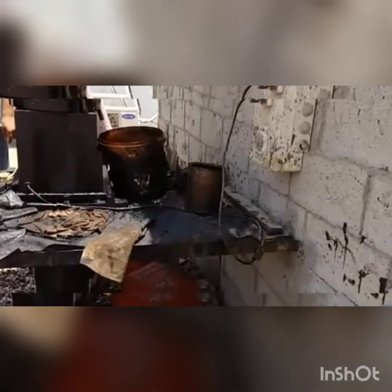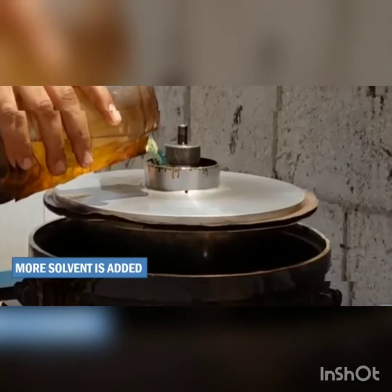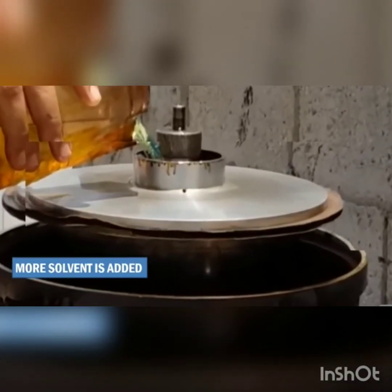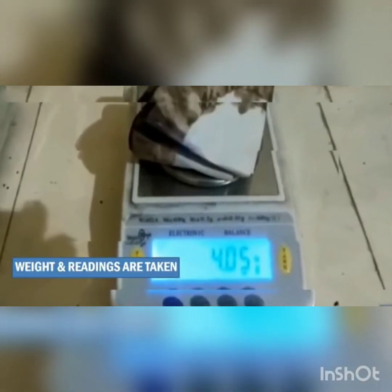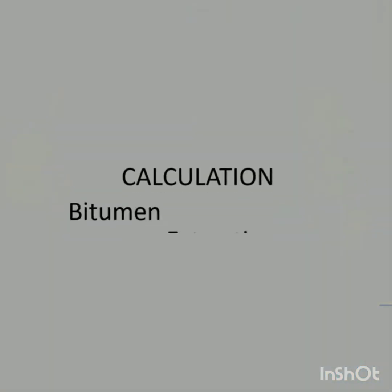The machine is allowed to revolve till solvent ceases to flow from the drain outlet. Allow the machine to stop and additional solvent is added in quantity of 200 ml or more depending on the amount of the sample. The fine fragments of mineral aggregates that are attached with the filter are carefully scratched, and then the weight of the filter and aggregate are noted.